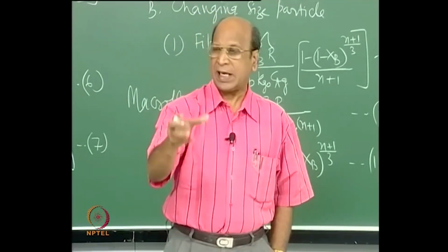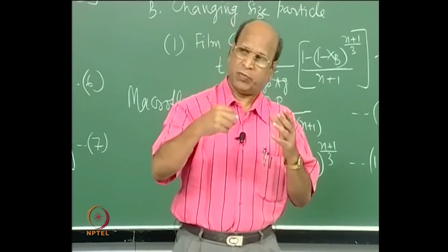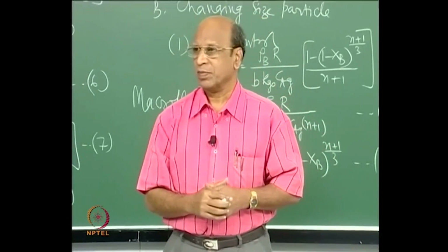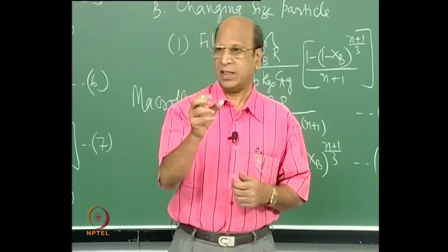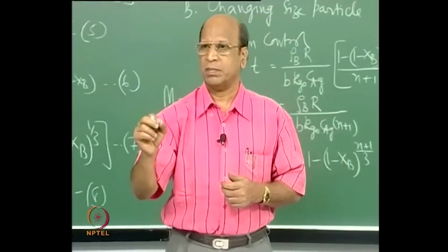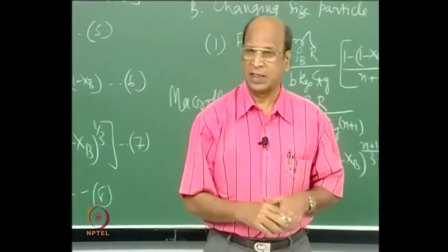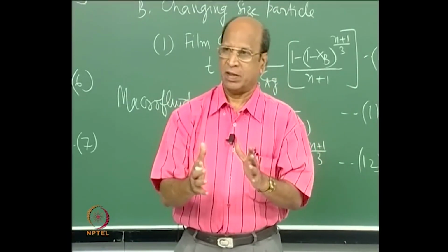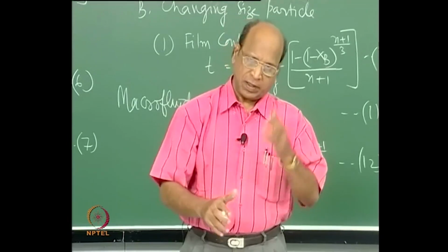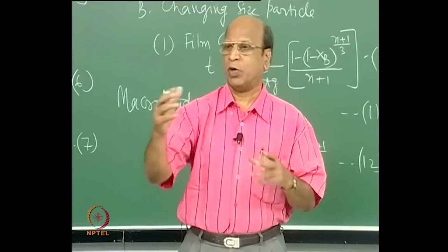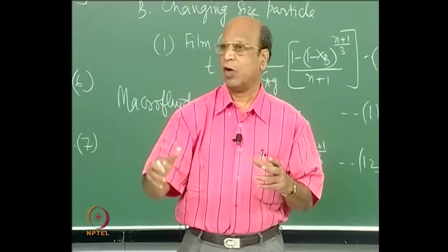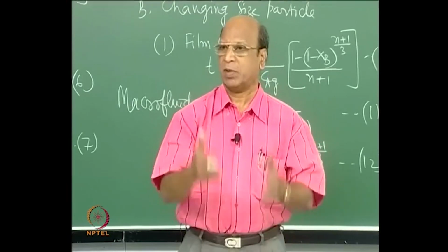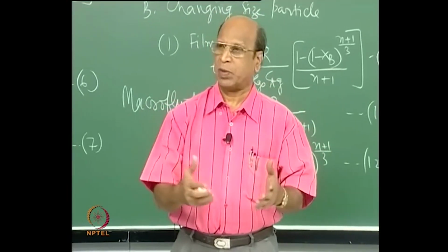So, if I look at my reactor and if I want to find out what is the fraction of material that is coming between the 10th minute and the 11th minute, right. So, that fraction is E(t) dt, where E(t) is the exit age distribution function and dt is the time interval, that is the fraction. So, now if I can add all those fractions, then I will know the total amount of material, how much time it took, then I can take the average of that, then I get the mean residence time or average residence time, all that you can get from RTD.